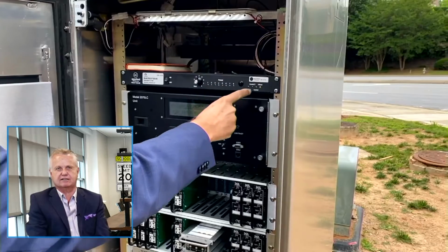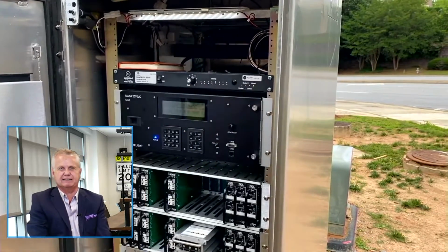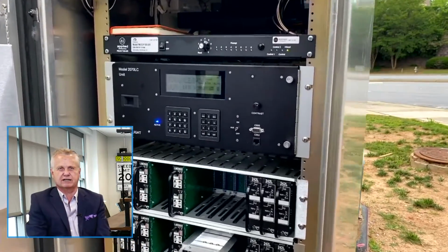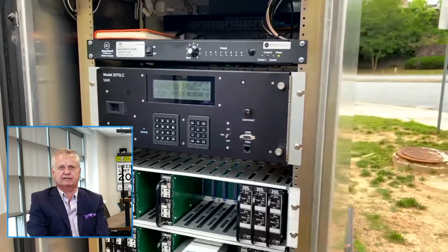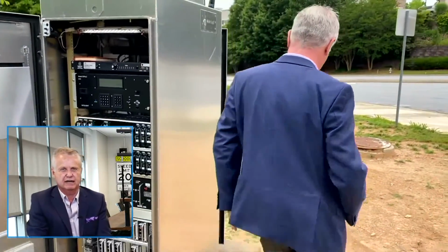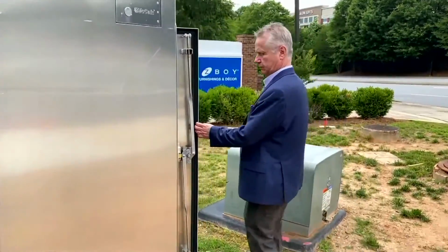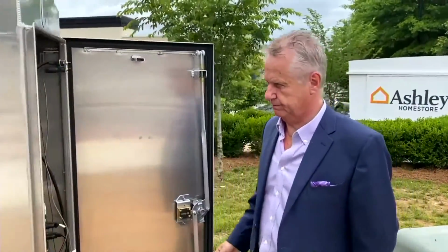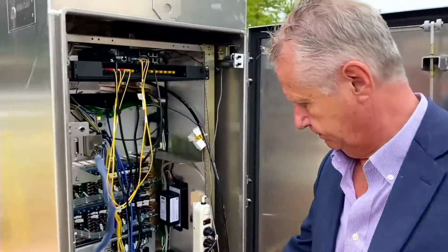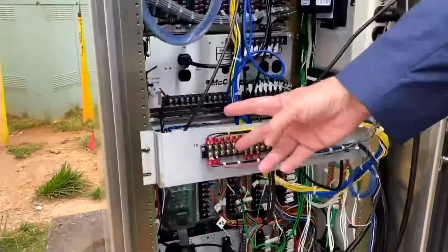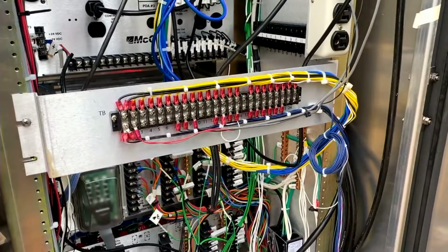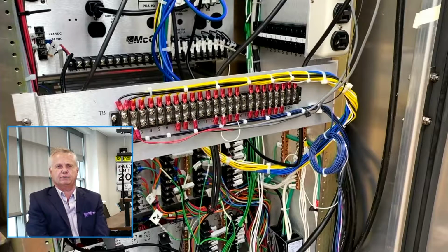So that's a little selector switch, and there are some LEDs which show the diagnostics of what's happening with your connected vehicle system at ground level, as opposed to having to climb up to the top of the pole and try and see what the LEDs are doing. This is where the wiring connects. If you just pause there, there's a number of traffic controllers that actually have hardwired preempt inputs. That's the panel that you see at the bottom there, where it is wired to the traffic controller.